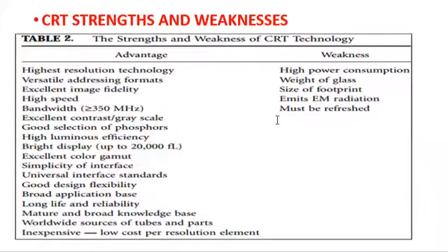Now, we have a table here showing the advantages, the strengths, and the disadvantages, the weaknesses, of the CRT. As you can see on the left hand side, I have the advantages, which are more. They include high resolution, versatile addressing format, excellent image fidelity, high speed, high bandwidth, excellent contrast, good selection of phosphors, and inexpensive, that is low cost of production.